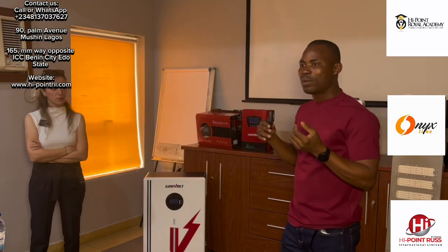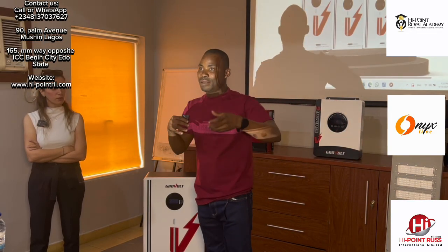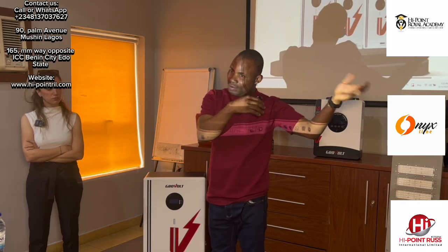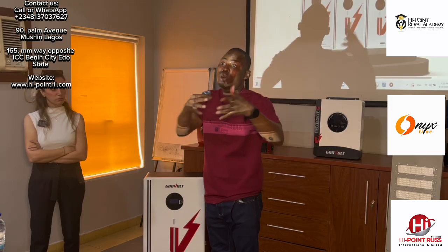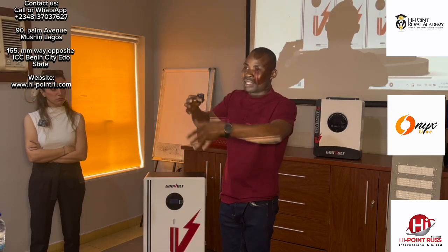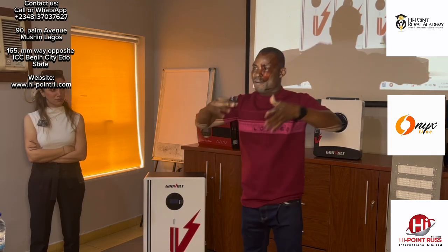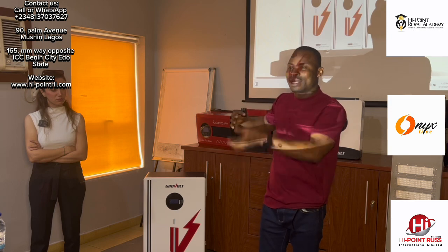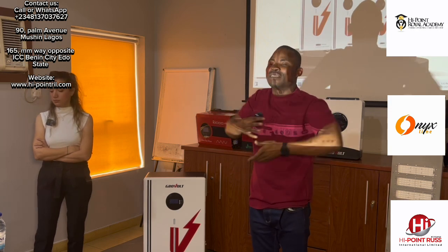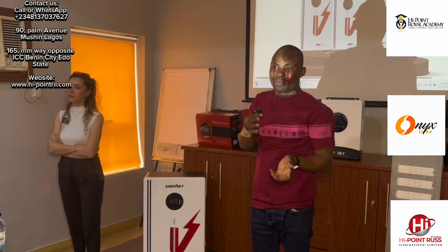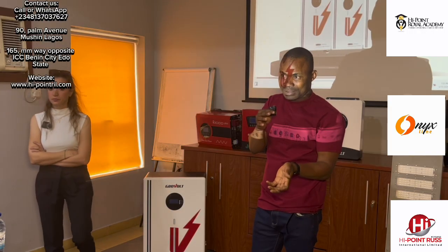Do you understand what we call refurbished cells? Yes. Like all these electric cars, when 16 cells are inside a battery pack and a particular cell is damaged, usually it's supposed to go for recycling, but what some companies do, not them, is pick out the good cells, feed them into a lithium case, replace that particular cell, rebrand it and sell it in the market at a much cheaper price, because there's a price war in the market.